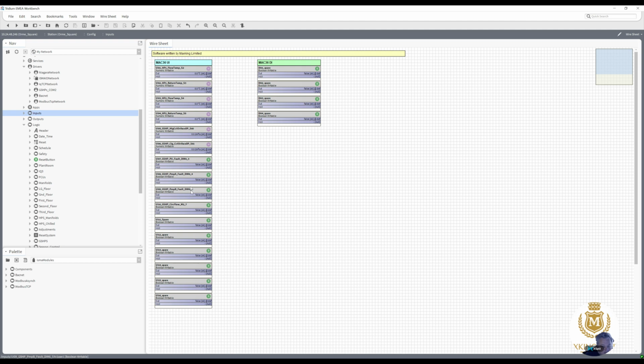So I'll put these notes here so I know where I'm taking the point from. It's just easier when I'm on site. And then UI10 is ground source heat pump circ flow. So if the pumps are flowing, that's on module 2 of the trend, point 7, input 7.